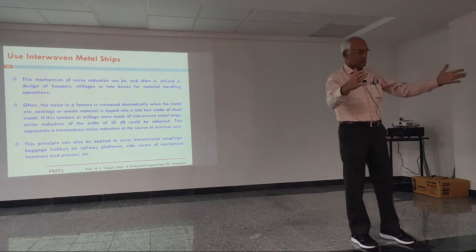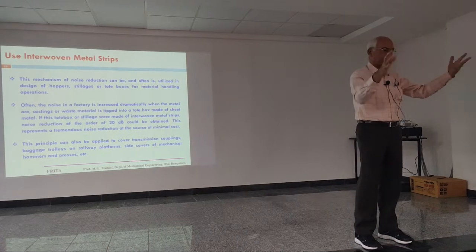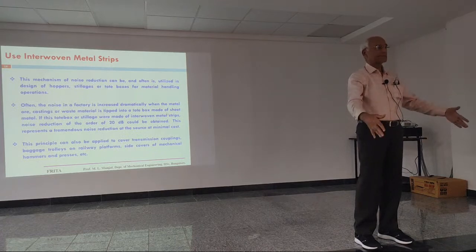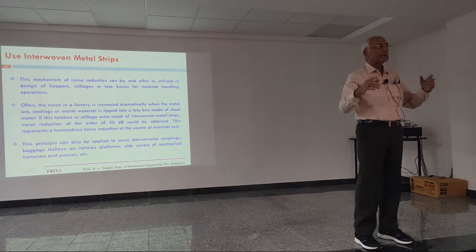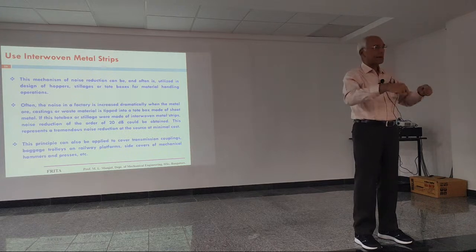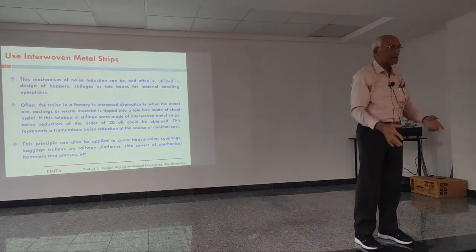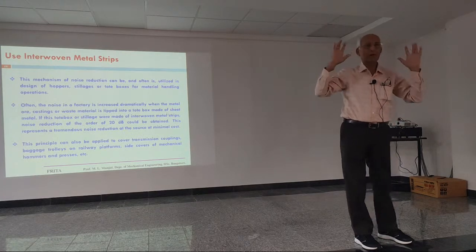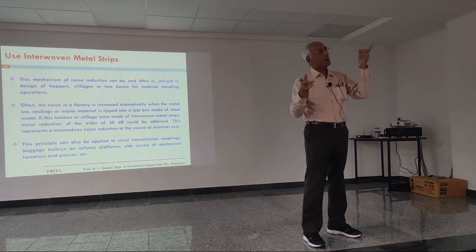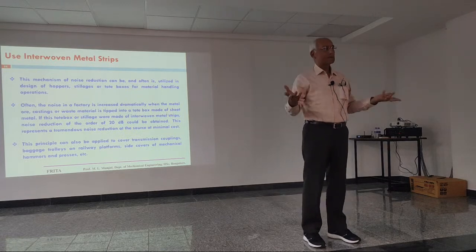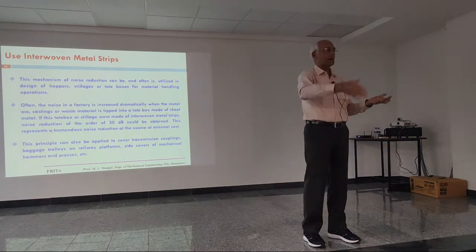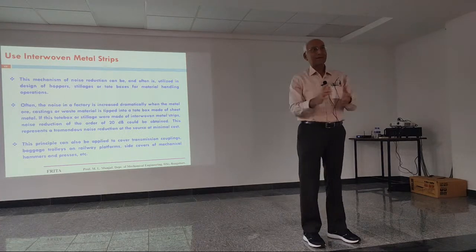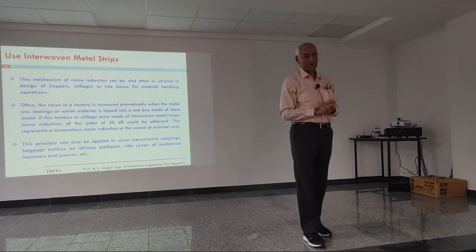And now the tote box is simply made like a bar, not a bar, just like this, all made of plates. So when this falls into that, all the surfaces of that tote box act as such big loudspeakers, and it's happening all the time because their business is that. All the time they are falling one after the other into the tote box, and the tote box is really vibrating and producing a lot of noise.